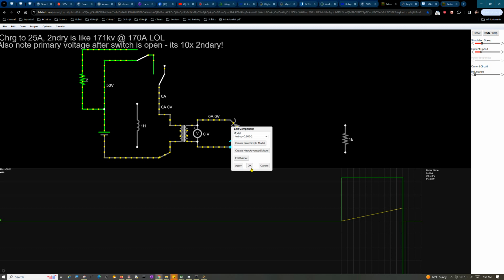So in one waveform, because again, if it's just a pure resistive load like we had before, it's going to be supplying that in 1/60th of a second. It's supplying 300 divided by 60, which is like 5 joules per cycle, just as a rough rule of thumb. So you got to kind of watch what kind of current you apply to this and everything, because it's not going to be maybe what you think.